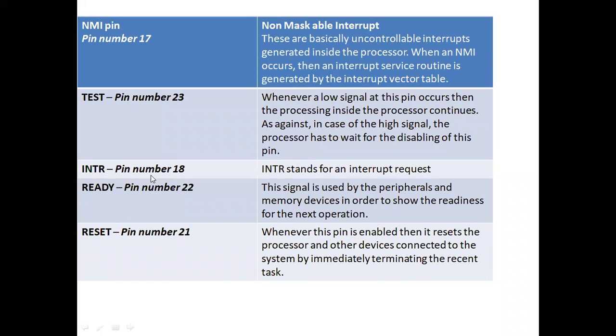Then the interrupt request pin. This is a very important pin. This is a hardware interrupt. We will learn the interrupt structure in the upcoming lecture, and at that time we will discuss it more. INTR stands for interrupt request. Here we can connect the hardware interrupt with the processor.